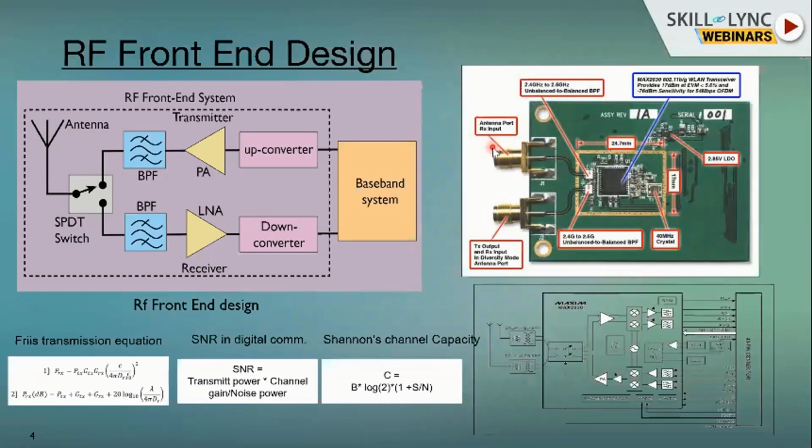There is a concept called half duplex or full duplex. With half duplex, like walkie-talkies, you receive first and after that you transmit, so it is one by one. Or there will be full duplex, where you transmit and receive at the same time. In this case you could use two antennas, but if you look at your mobile phone, you won't see two antennas. Generally you will see only one antenna. So that's called a full duplex transceiver, right?